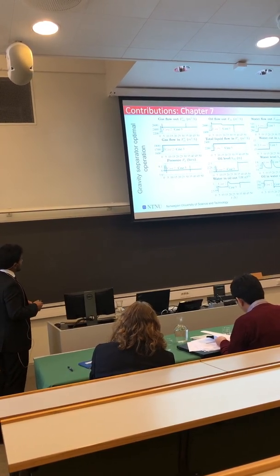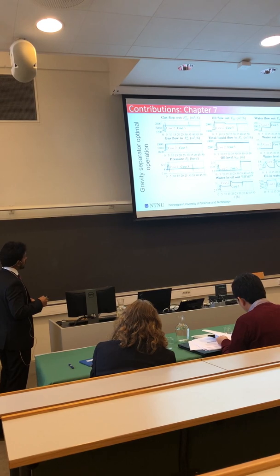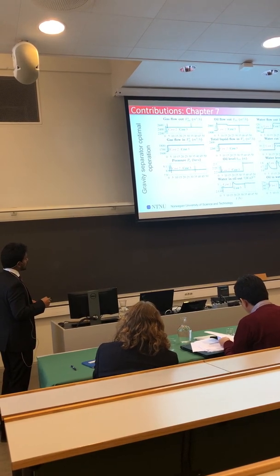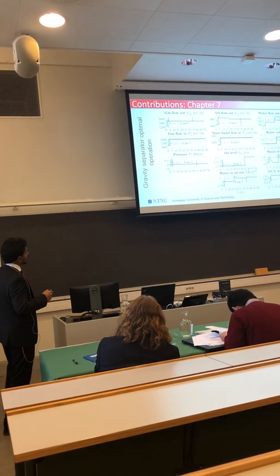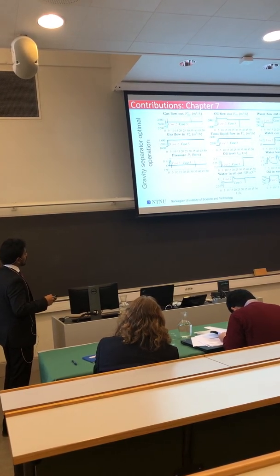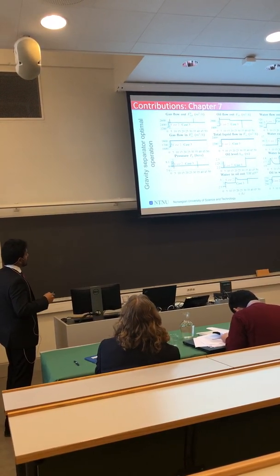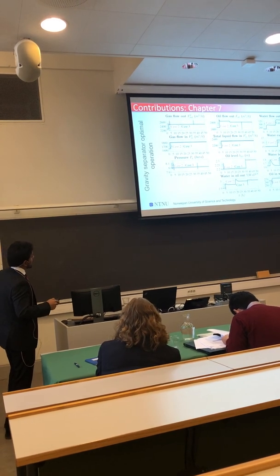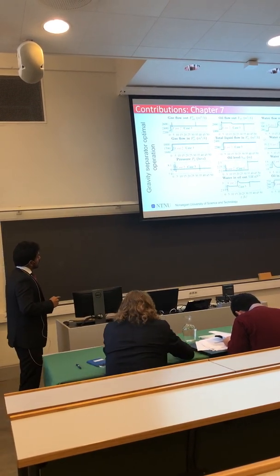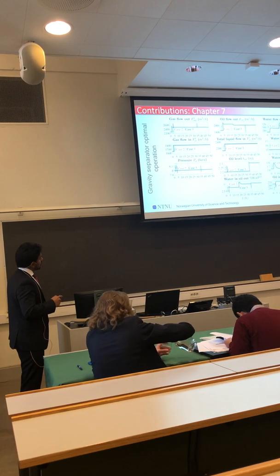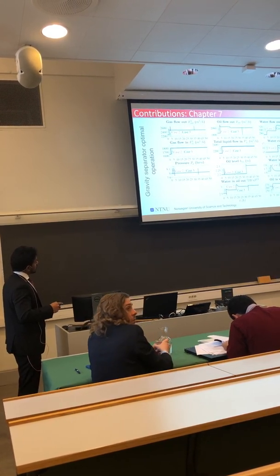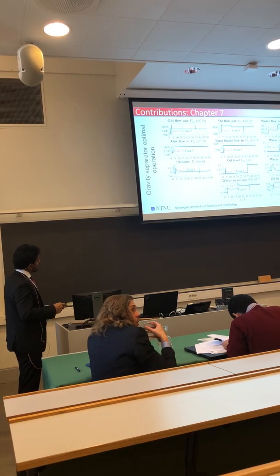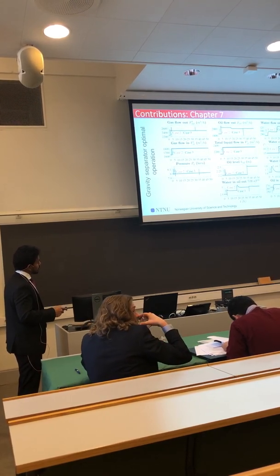I have the gravity separator results. Here this row demonstrates the 3 controlled variables: the pressure, the oil level, and the water level being controlled using the gas outflow, oil outflow, and water outflow correspondingly. We have some other things here. These are the disturbances, case 1, case 2, and case 3, demonstrated at different time points, and we see how this control structure responds to that.